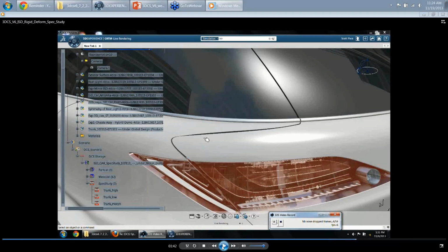Once again, this is not just on cars. It's on airplanes. It's on electronics goods. If it does not look good, there's a perceived quality concern that this is not a good product just because of a look. So up front in the dimensional management process and doing analysis, we want to say, what will this look like to the customer?